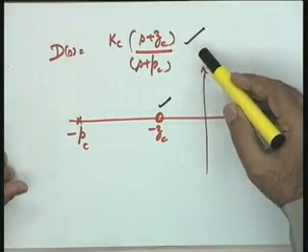I think right at this stage it will be appropriate if I take an example; the attributes of the phase lag compensator will be taken later. I give a comment here that the PD controller, which we have discussed in so many places in this classroom, is a special case of the phase lead compensator.